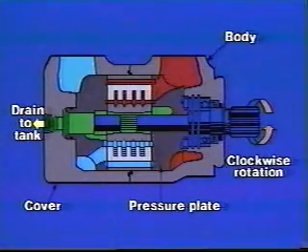External draining in this unit is accomplished through a port in the cover. Just as with a vane-type pump, if we want to change motor displacement in a given frame size, all we do is simply change the cam ring to one that is wider, larger, or smaller in diameter.